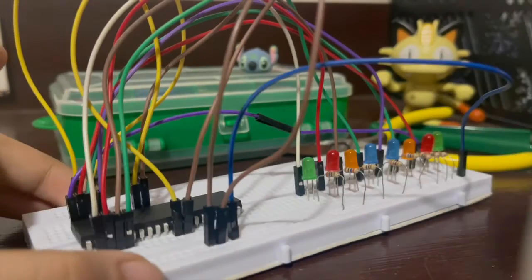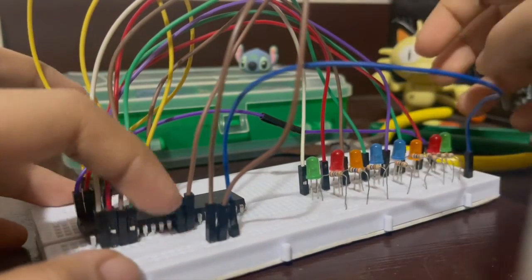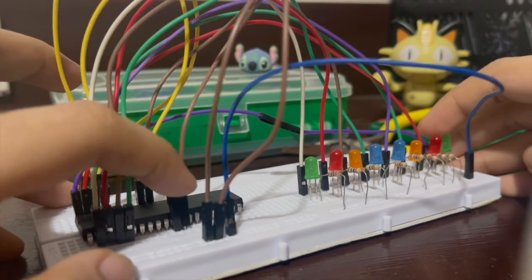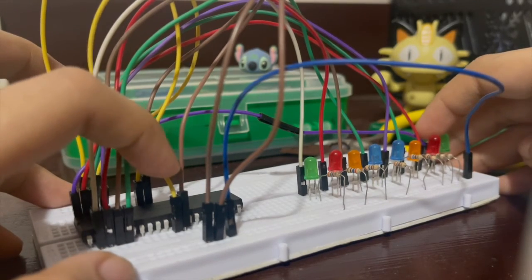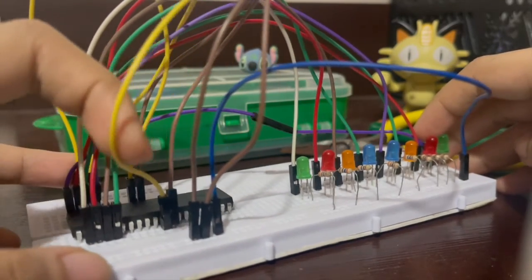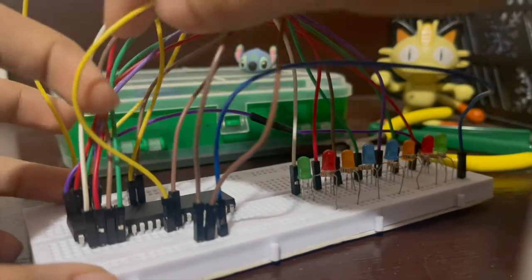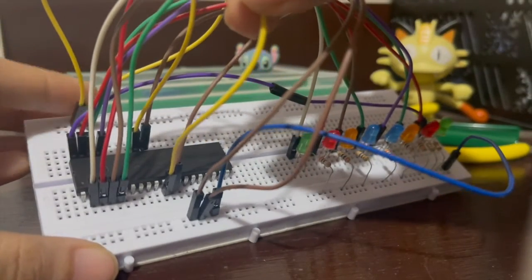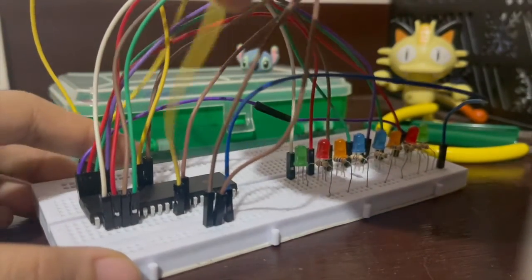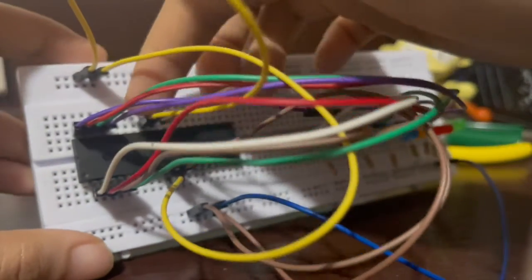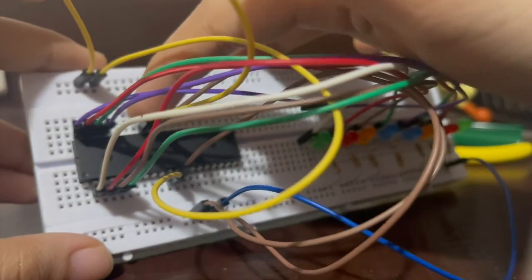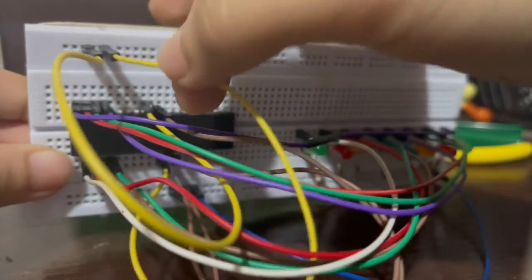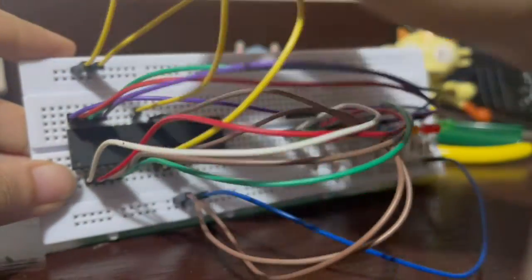sides of the LED. And here you can also observe some wires at the 11th and 12th pin. This yellow here represents the VDD, which should be connected to the positive side of the breadboard, the positive terminal. And at the same time, the yellow here is also the VDD, which is at pin number 32. There. It's also connected to the positive terminal.